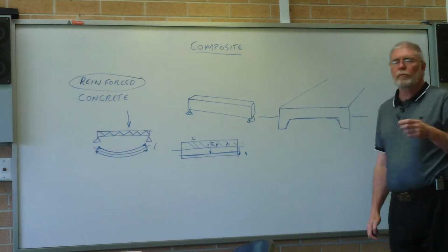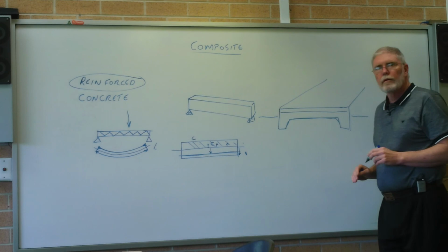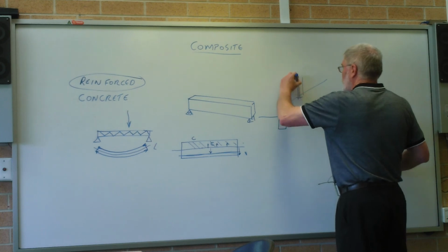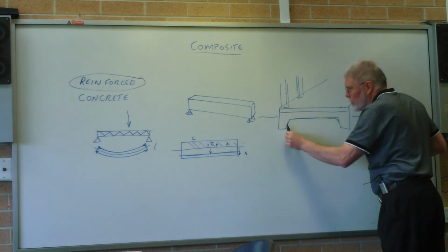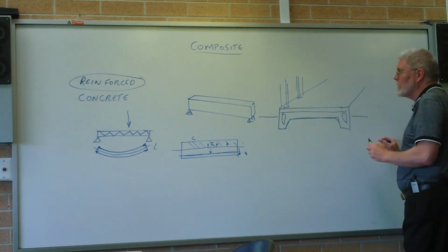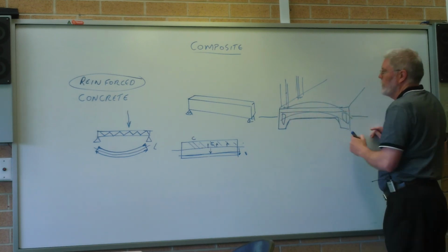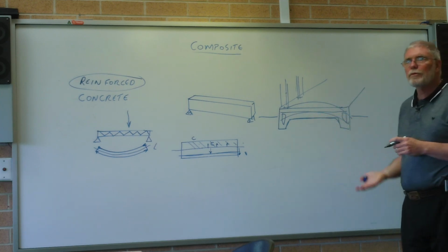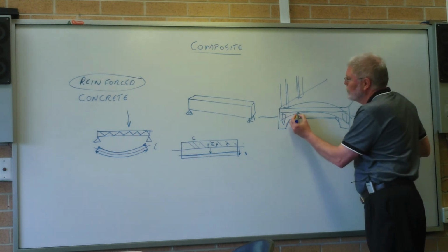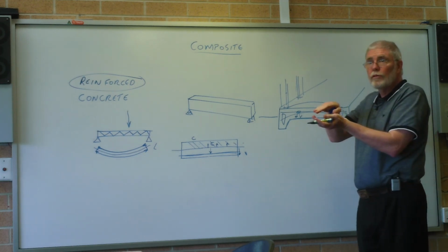Where would you put the reinforcement this time? They tend to put it towards the top, because the loading comes from the beams or from the roof trusses and down through the studs onto these. The footings hold it in and stop it from moving, and they will put reinforcement into here as well to keep that bound together. But what's happening to the raft is it wants to bend that way with the loading coming down on the side. So in these types of structures, you put it towards the top. And you may notice when you see people pouring concrete, they put these little metal foot things, plates and little cup sort of things to sit the reinforcement on to raise it up into the material.